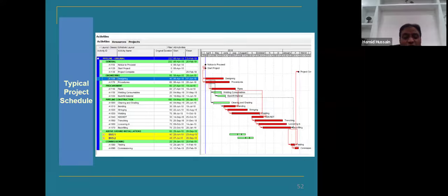Civil engineers cannot go ahead. Or layout of a pipe rack or layout of a cable tray for instrumentation and electrical cannot go ahead without the plot plan. So these are the sequential engineering. Generally, this should be followed religiously. But nowadays, I have observed that people are skipping this one. But it is advisable not to skip this schedule. And this is a sequential schedule. This you cannot overlap. You can do some sort of engineering in parallel, but you have to have sequential engineering.